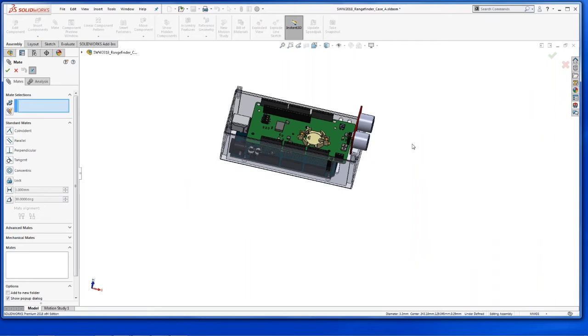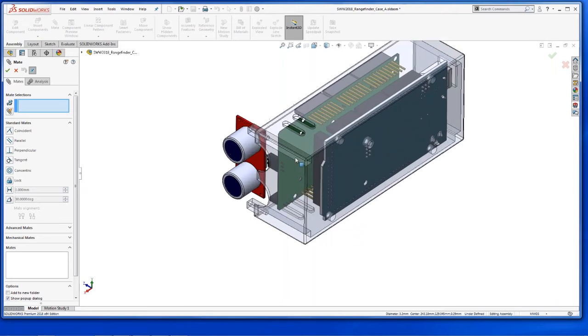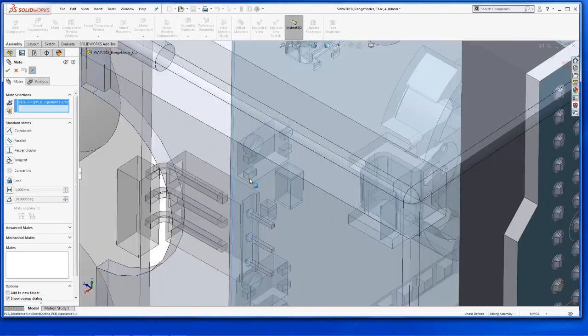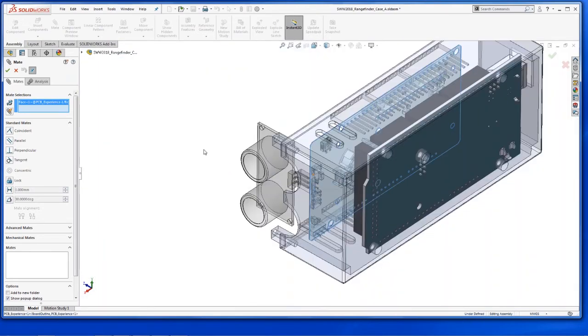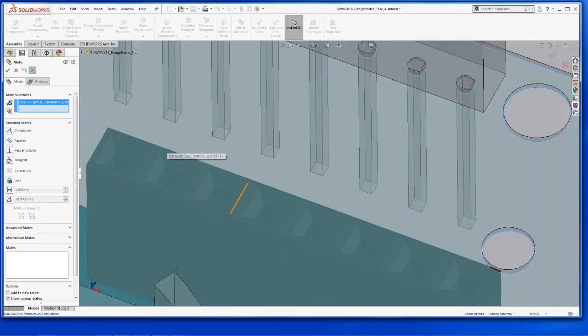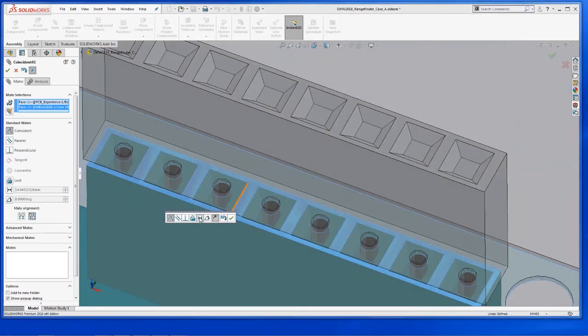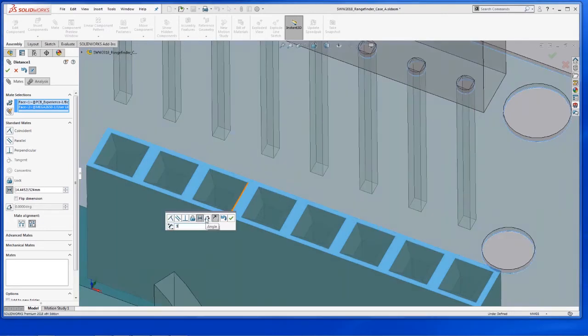Right? We've lined them up in a position. Now we need to set the overall height. So we just pick the back of the board, and we need that to be positioned inside of the header on the secondary PCB. And we need to set that distance at 3.2 millimeters.